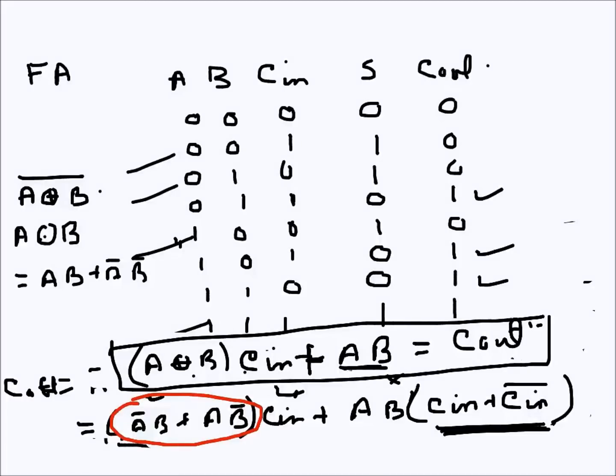So basically a half adder is just adding 2 bits without considering any previous stage, and then getting as output the sum and the carry out, while a full adder is considering a carry in as well, so adding 2 bits with a carry in from the previous stage, and then having an output of sum and carry out. So full adders can be added in stages to get a multiple bit addition.